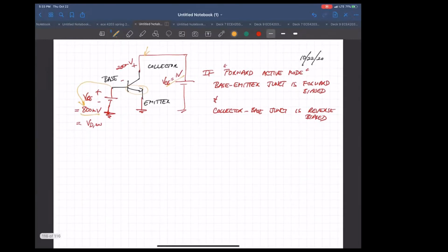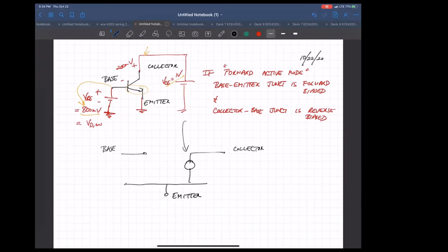And if we had that, we calculated a simple model. So this is a three-terminal device. This is the emitter, this is the base, this is the collector. And so if we did all this, the collector current would be I sub S exponential of VBE over VT.